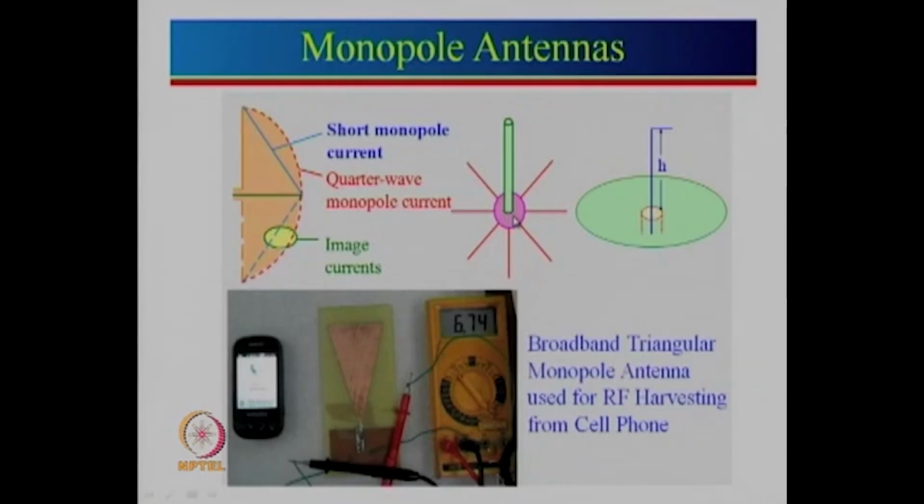In fact, for medium wave transmission, which I mentioned in the last lecture, a medium wave transmitter at 1 megahertz would require an antenna of the height of 75 meter, and there we need to provide a ground plane. Now, earth may not always be a perfect ground plane, so a lot of these radial lines are put on the ground, and these are long radial lines which have to be put.